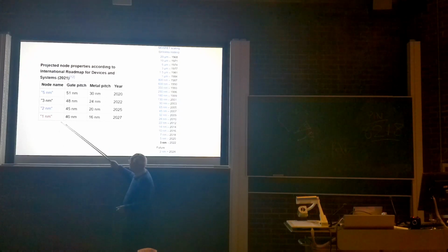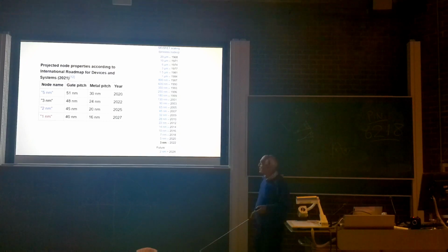And so these commercial guys are talking about their 1.8 nanometer system and this technology, and even below that, 0.9, etc. But it's all hype. It's nothing to do with the original definition, which was the gate pitch, which is the central part of a CMOS type transistor.